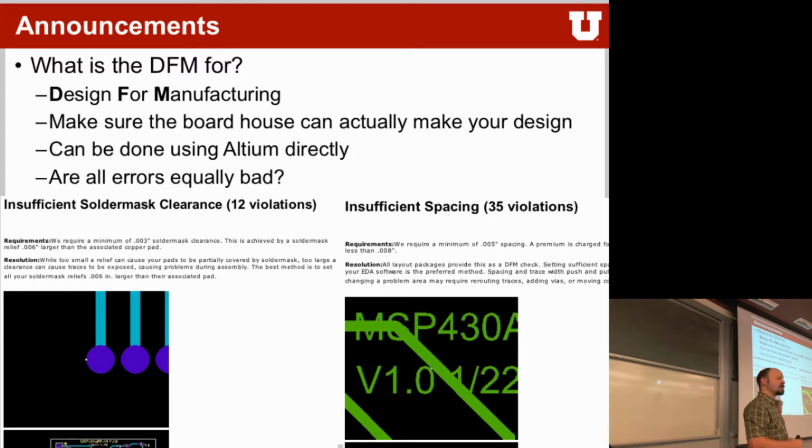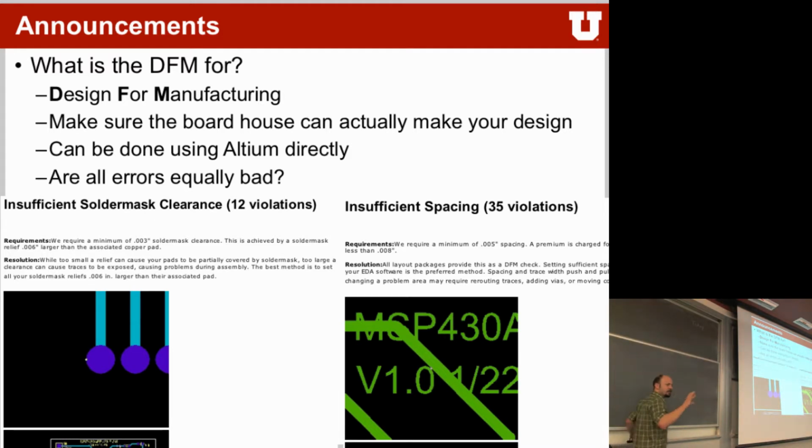Now, that said, sometimes you actually want to do that. So what happens in the design is the following. If you look at it in the physical structure, you have your PCB that sits here, right? This is FR4 material, which is fiberglass. That's the stuff that's in between the sandwich. Up on top, you have a copper trace, or a hole, or something like that. And then on top of this, they put the solder mask to basically make these things not conductive to the outside so you can actually touch them without actually touching the metal. So if it's just a trace, you get covered up like this. Right? That's what we want.